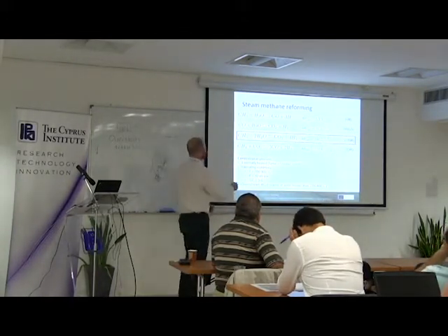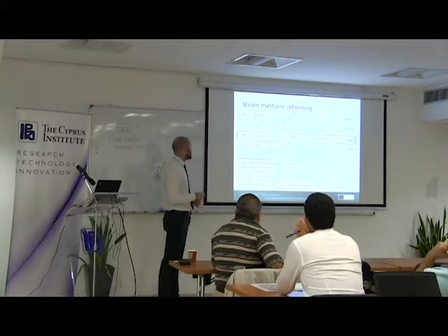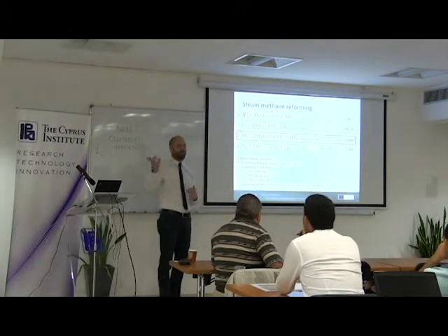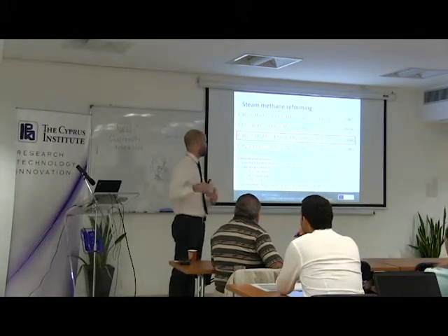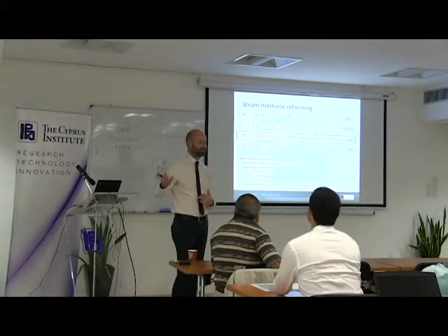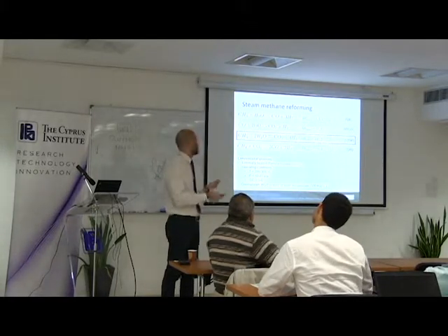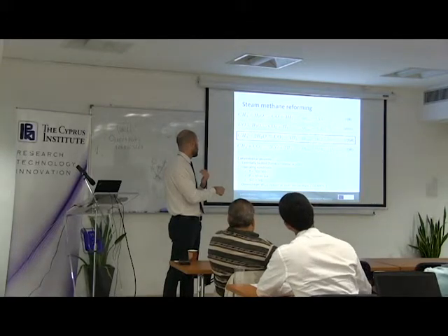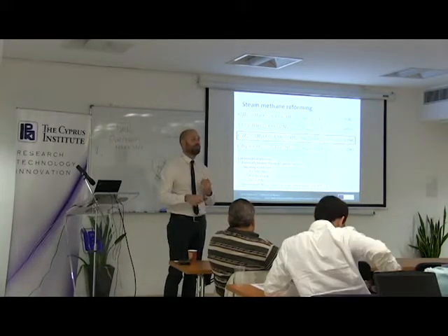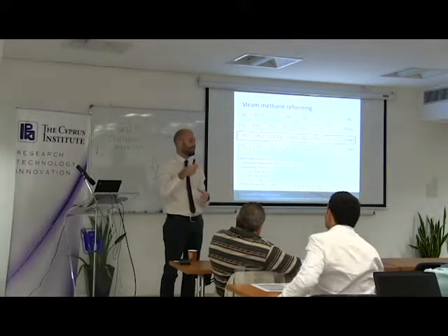In the conventional process, which is the most deployed today, you carry out this reaction. You must boil the water, you must produce the steam, which is very energy consuming. You must heat up the methane. Steam and methane must be heated up to slightly less than this temperature here, and fed to reactors, which are tubes filled with a catalyst.